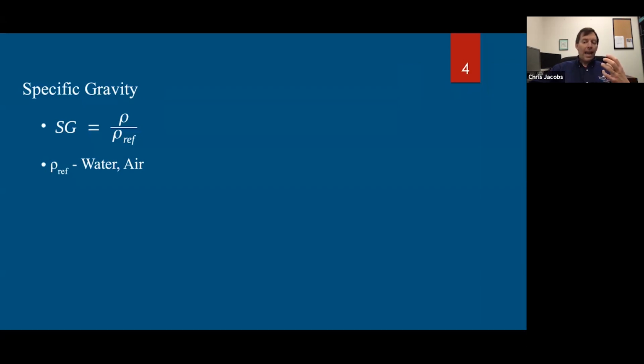If we are measuring air or our gas, and either one of those are not at the normal temperature of 20 degrees Celsius and 1 atmosphere, we will not get an accurate comparison between the two, and therefore the density will not be accurate. So it is important to measure specific gravity at the same temperature and pressure for both substances. And I alluded to that briefly before with how the gravity balance works and the other balance systems, direct weighing.